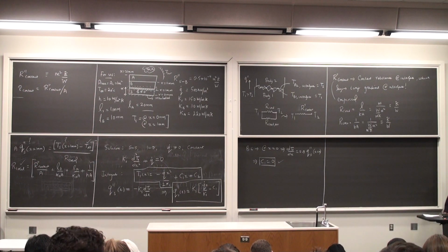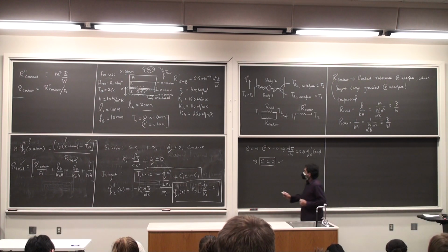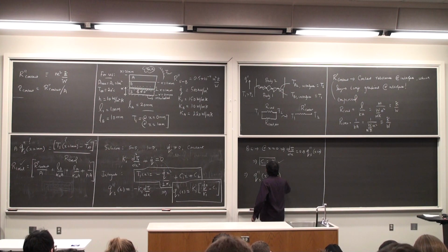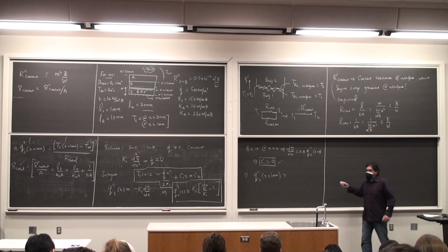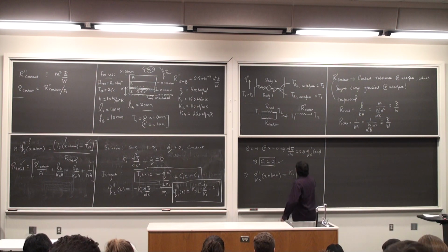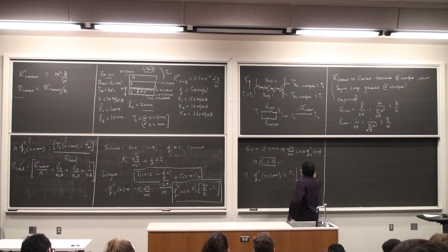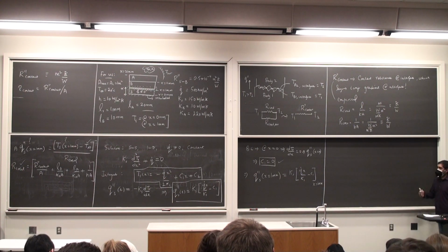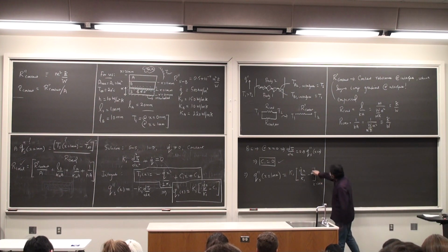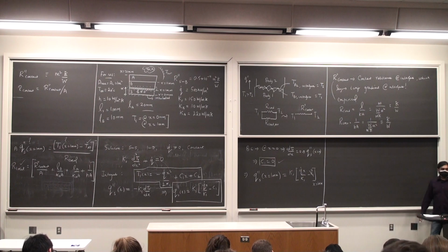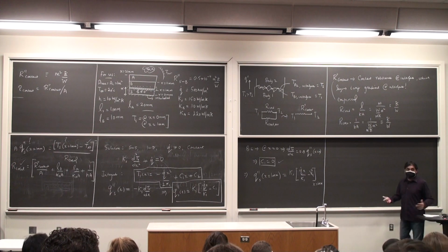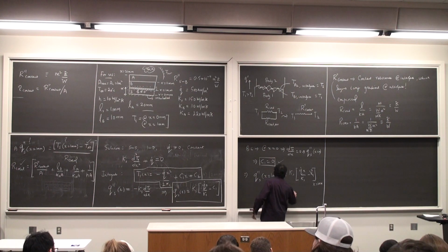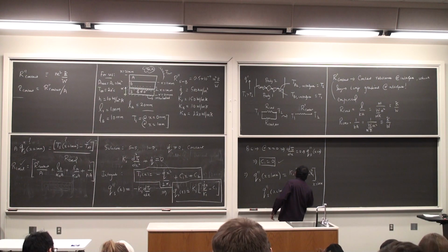So if C1 is 0, I can actually calculate the flux at x is equal to 1 millimeter, right? So this tells me q double prime at x is equal to 1 millimeter is Ks times (q dot x by Ks minus C1) evaluated at this particular value. C1 is obviously 0. Ks and Ks cancel each other out. x is equal to 1 millimeter. q dot is 500 kilowatts per meter cube. And so if I substitute, q double prime is 500 watts per meter square.